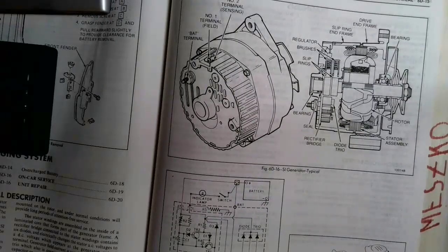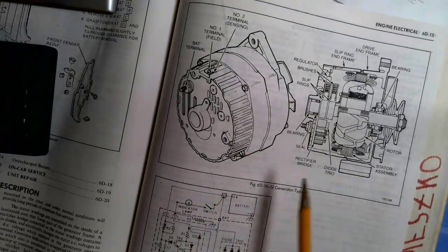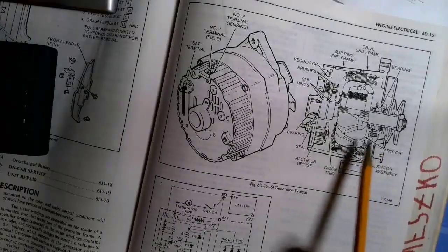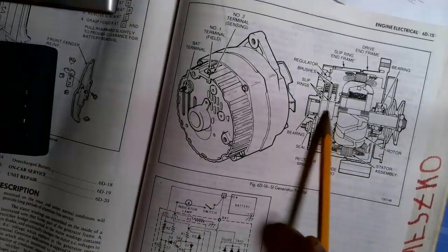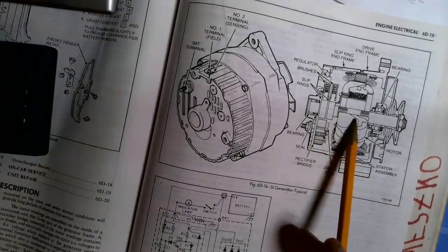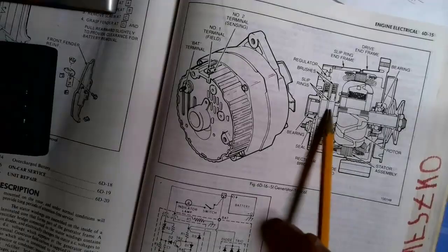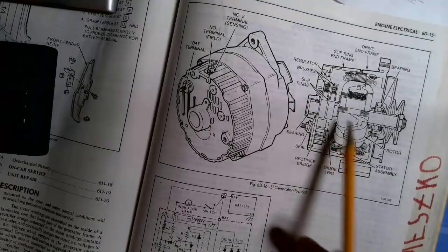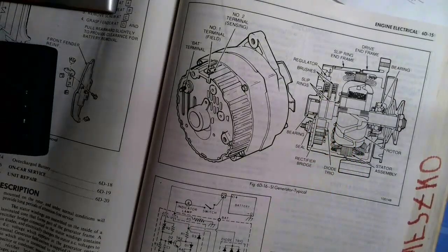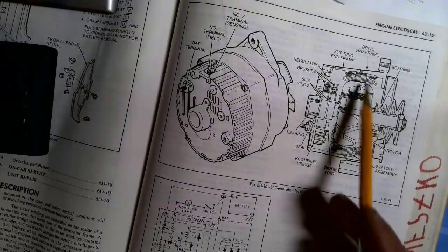Okay, here's a picture of the alternator, and then this is a cutaway view showing the pulley on the end, the shaft, and the slip rings that conduct electric power to the rotor here. The rotor is just an electromagnet, and the power for the electromagnet comes through these slip rings. The brushes rub on the slip rings, so that the rotor can rotate and still maintain connection with the power source for the electromagnet. And the stator here is where the coils are that extract the AC power from this machine.